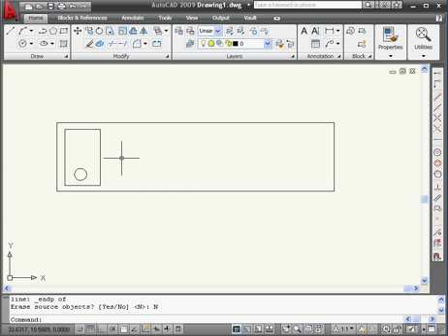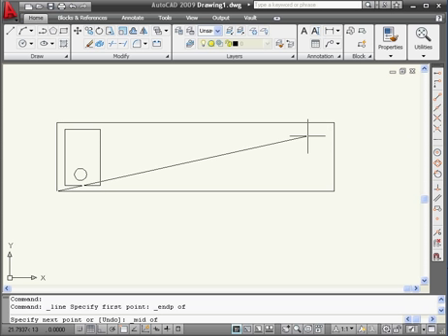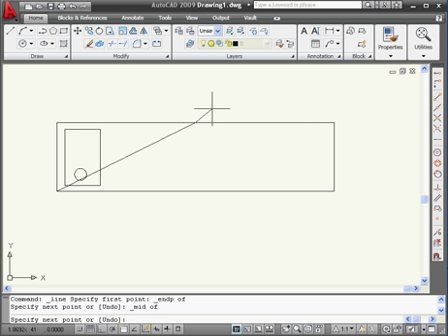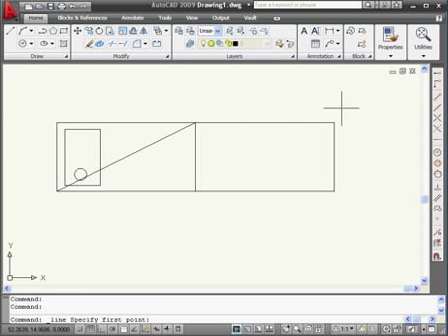Here I'm going to create 4 copies of this circle and rectangle within this larger rectangle. First thing to do is create some support geometry. Activate the Line tool, Snap to End, select here, Snap to Midpoint, select here. Snap to Midpoint again. Right-click and enter.